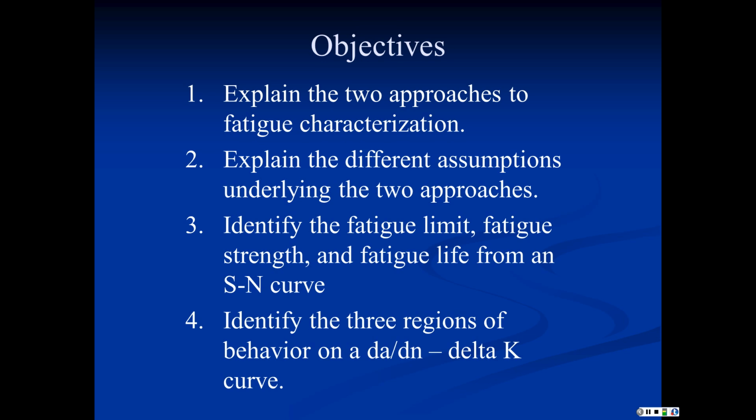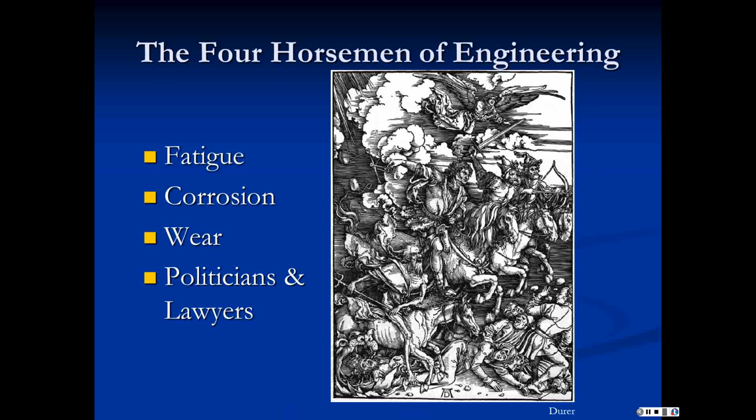And then we're going to identify or define the fatigue limit, fatigue strength, fatigue life. I'll show you what an S-N curve looks like. We're going to introduce da/dN and delta K curves, and we'll do some work with those in class.